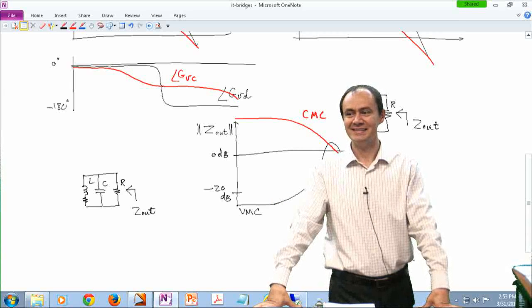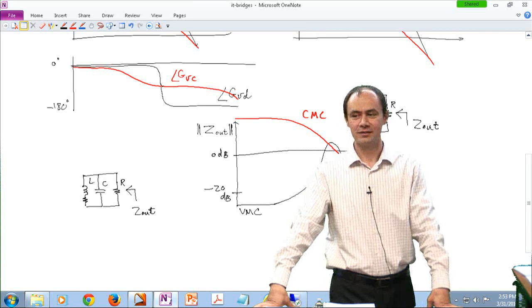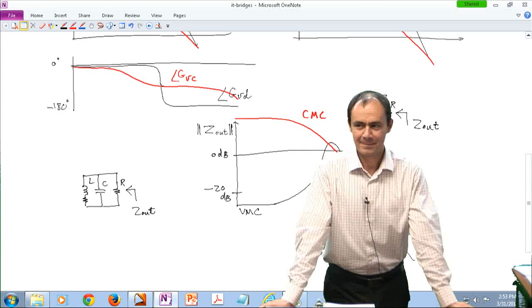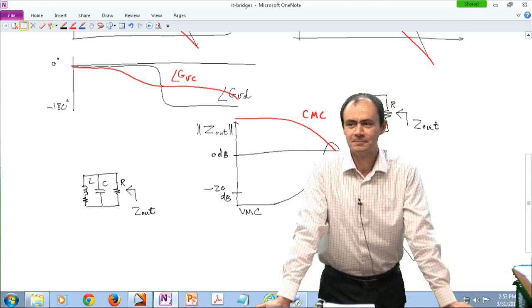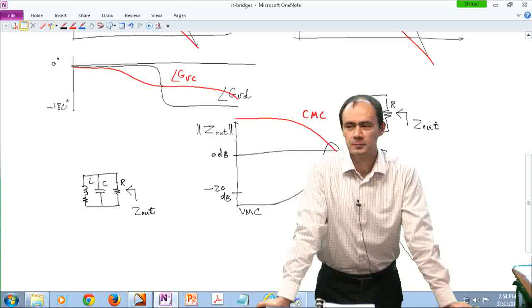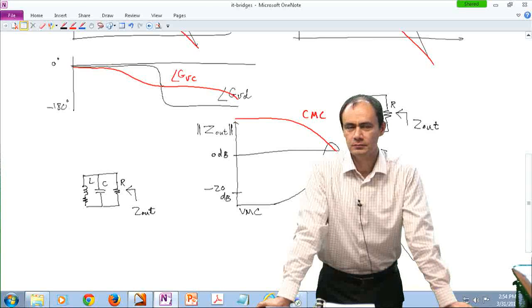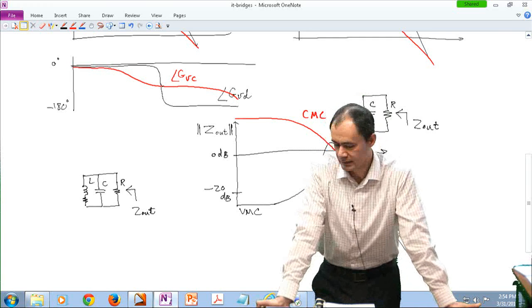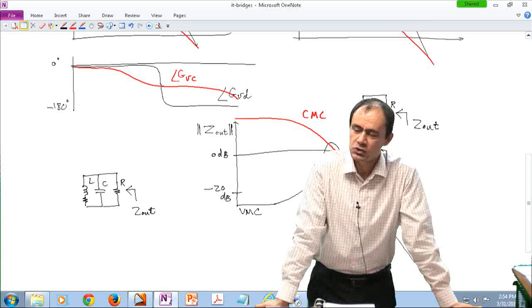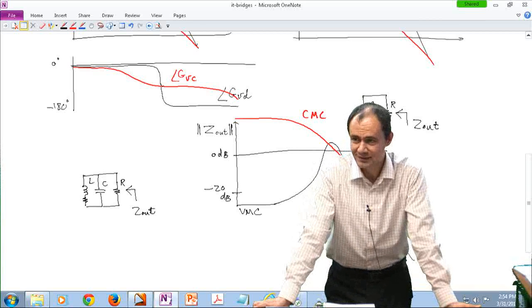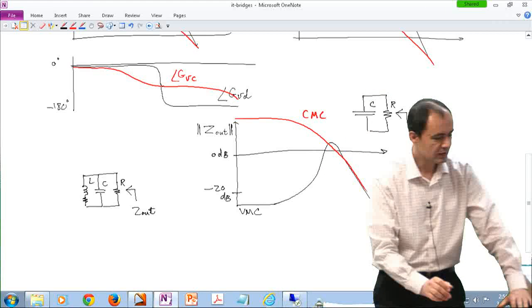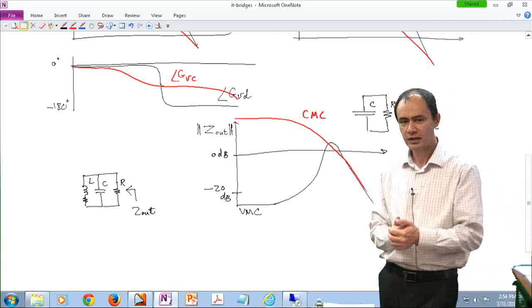We had a V out and we had a duty ratio for the first part, and then we had a V out and again a duty ratio for the second part. So I know that I have a specific output voltage to be met. Would I just have to tune the controller every time? Oh, you mean if you want to regulate the output voltage? Now I have a different requirement for an output voltage. Is your output voltage supposed to be constant? No, it was 19.2 and then it was 14.4. Okay. So if you have an application like that, and actually we have real applications like this.